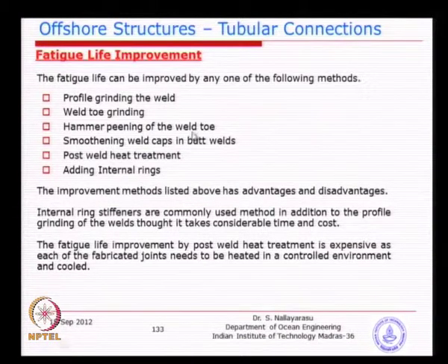Whereas, the smoothing of weld caps is similar to the weld profiling, basically the surface profiling. All these 4 methods are mentioned in API, but directly giving the recommendation to calculate the design life is only for the first one. The profile weld, there is a formula to calculate the increased design life.